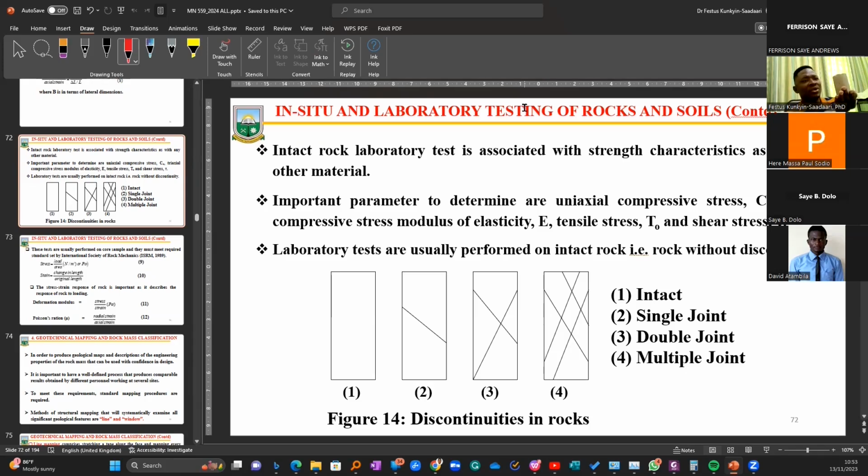And this is going to be a representation of the strength of the rock you have there in your mind. What comes to mind? If I pick any sample that already has failures on it, I will end up testing and getting lower values, which will mean that the rock is not competent enough. And so I have to inform management. If the mineral we are interested in is of a higher grade we can't do without, then they have to provide extra funds for us to provide support. Yet in a natural sense, the rock itself was competent, but because we didn't pick our sample from the right locations.